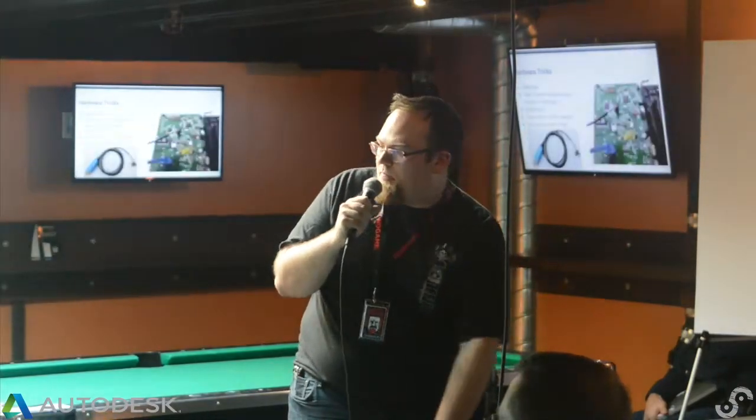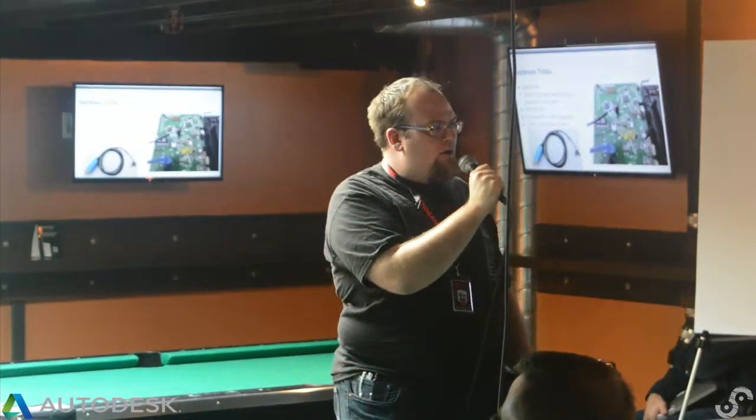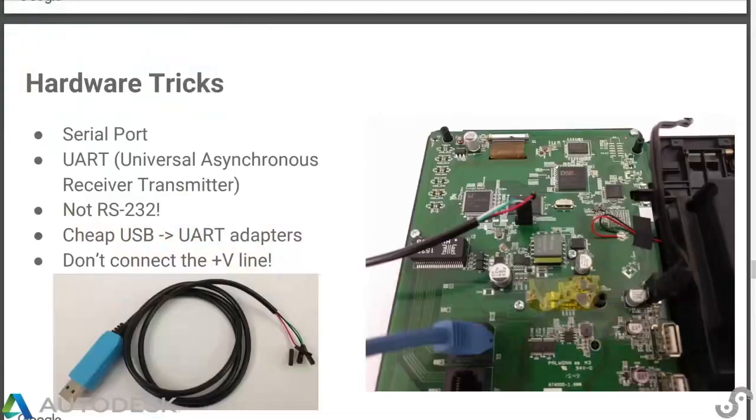And there's this wonderful adapter you can buy. You don't want to connect directly to a hardware serial port, by the way. Hardware serial port is 12 volts. This board runs at 3.3 volts. You put 12 volts into a 3.3 volt board, you will let out the magic smoke. Your assessment will be over until you buy another device.